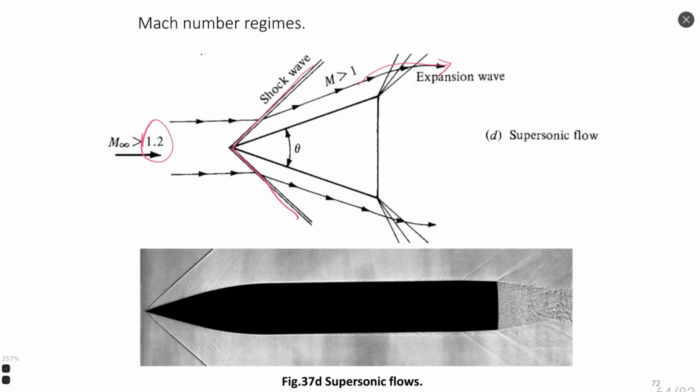So a shock wave increases pressure inside the flow, and you probably know that at a far distance from this body we will also have the same pressure as before, right? For example, an airplane flies. Before the airplane, we had 1 atmosphere, and very far from this airplane, we also have 1 atmosphere. How is it done? If we have shock waves, it just increases